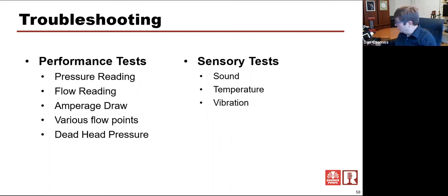And one of the things that I wanted to show you is this FLIR thermal thermometer. It's a little device that looks like a cell phone actually. This is a camera that senses temperature points on a given system or bearings or an electrical box. It's pretty useful. If you look at it here, looking at me, you'll see a temperature variance, and these things are about $600 or so. It's really nice for a service department to have.